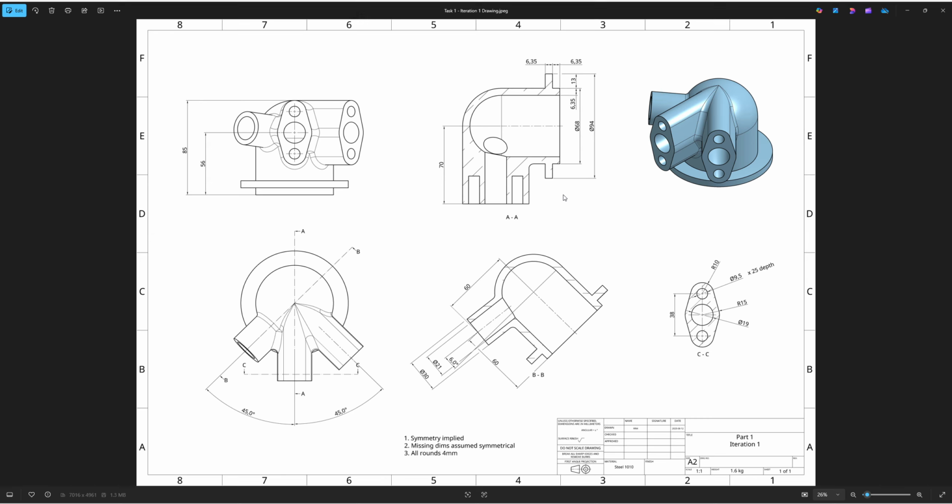The next bit we want to do is attach this part onto our main sketch. If we look at it, we have the circular parts. We're going to do those in a second. We're going to be doing this main bit, which goes up to the top, and we know that we've got a radius on the outside, this arrow here, of 15, a radius of 10 on the outside, and in terms of height, what are we looking at? We're going to want it to be 56 up there to the center part, so we can have a little look at that in a second.